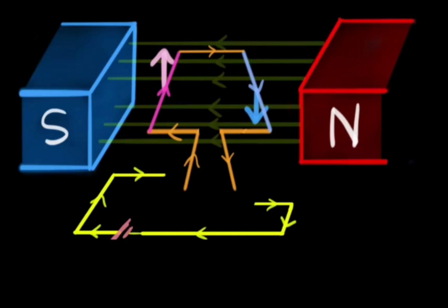The value of the back EMF is always less than the applied voltage, though the difference is small when the machine is running under normal conditions. And this is the difference between the two quantities which actually drives the current through the resistance of the armature circuit.